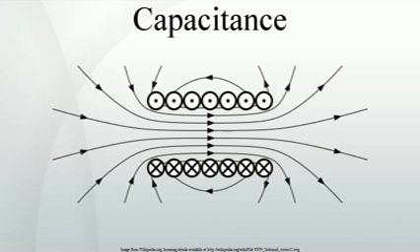Stray capacitance. Any two adjacent conductors can be considered a capacitor, though the capacitance is small unless the conductors are close together for long distances or over a large area. This, often unwanted, effect is termed stray capacitance. Stray capacitance can allow signals to leak between otherwise isolated circuits, an effect called crosstalk, and it can be a limiting factor for proper functioning of circuits at high frequency.